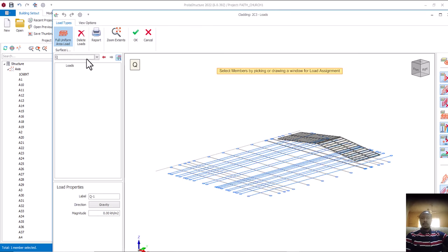Now, for non-accessible roofs, there are some roofs that are not accessible once they finish roofing because of the slope, isn't it? So in those cases, we can reduce the load to between 0.3 and 0.5. Are we together? But the most commonly used design value is 0.6 kilonewton per meter square. So in terms of your imposed load, according to Eurocode, it is 0.6 kilonewton, which means in this place we are going to enter 0.6. Are we together? 0.6 kilonewton per meter square.